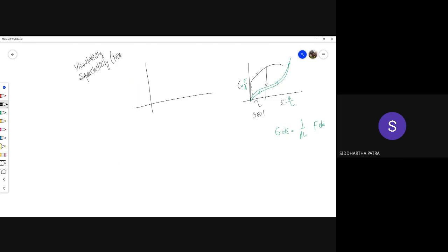There is an alloy called nitinol, which actually goes through phase transformation from austenite to martensite in the process. Viscoelasticity is typically observed in glass. This is typically observed in rubber-like materials, and this behavior is classified as hyperelasticity.